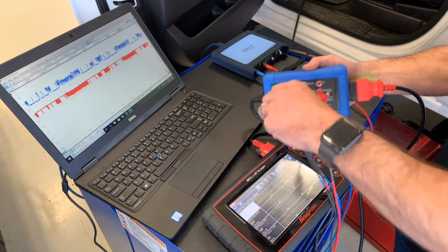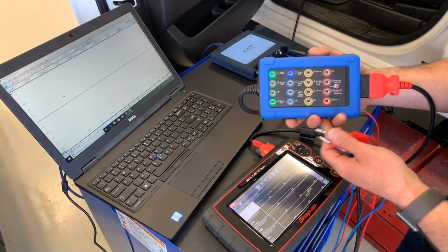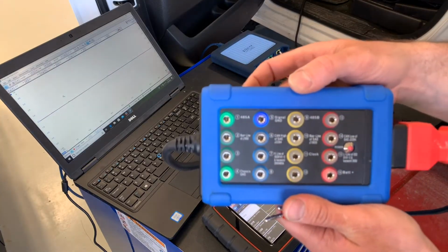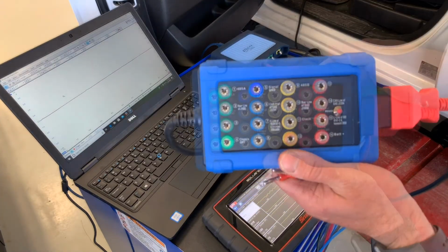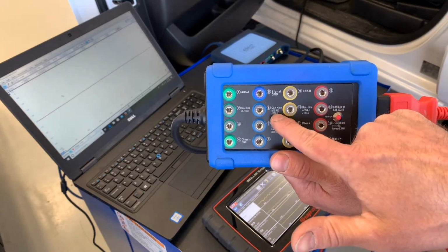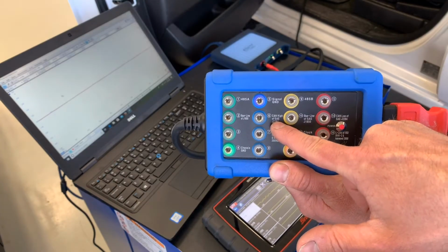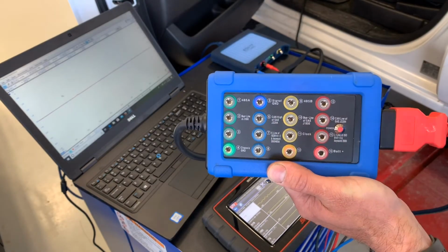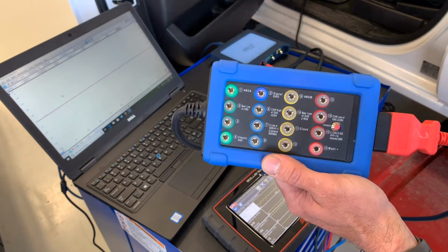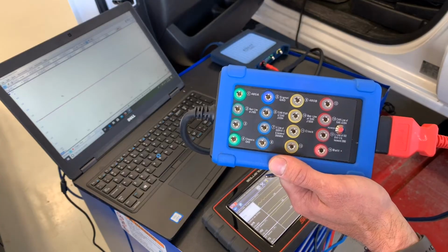So on here, I've got a handful of things plugged in. I'll move some of them so we can take a look. So if we look, this Breakout Box is really great in that it's got a lot of notes. And so standardized CAN pinouts, you can see some of these say SAE. And so that tells me that that's a standardized connection. And so 6 and 14 are the typical CAN communication pins on a DLC. They are the standardized pins. And so 6 is the high, and then 14 is the low.